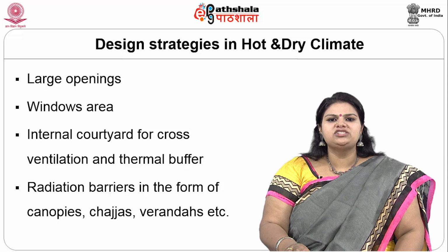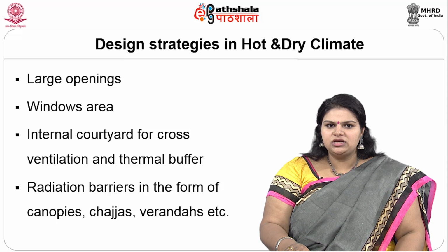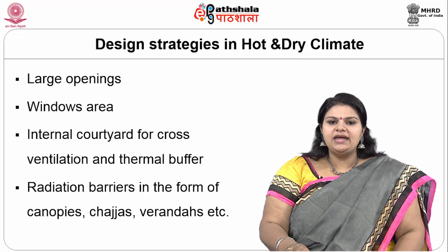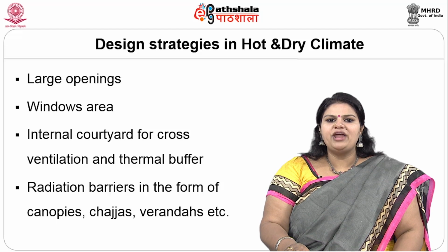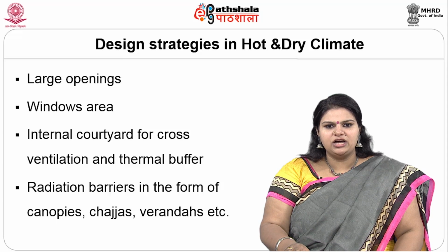If you look at the design strategies in hot and dry climates, you need to have large openings, great window area, internal courtyard for cross ventilation and thermal buffers, radiation barriers in the form of canopies, chhajjas, verandas, etc.